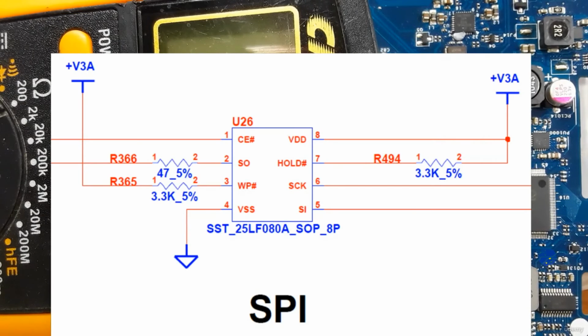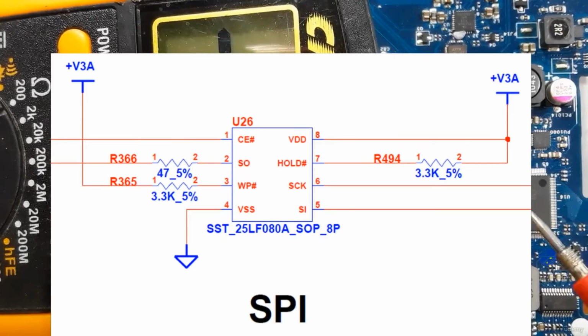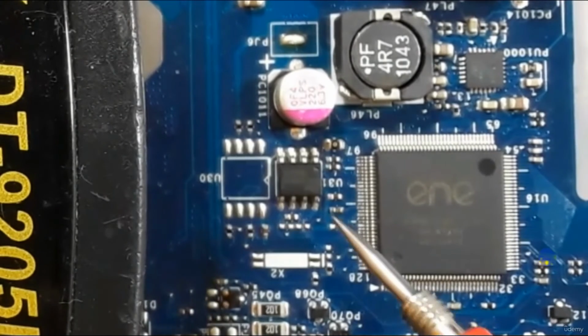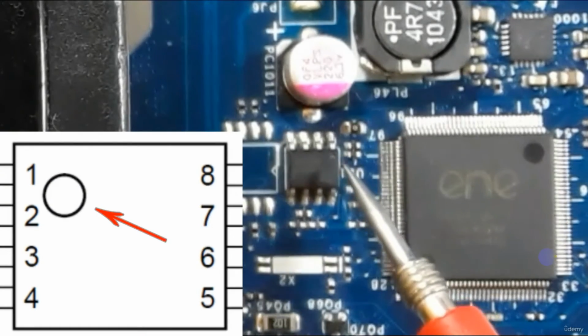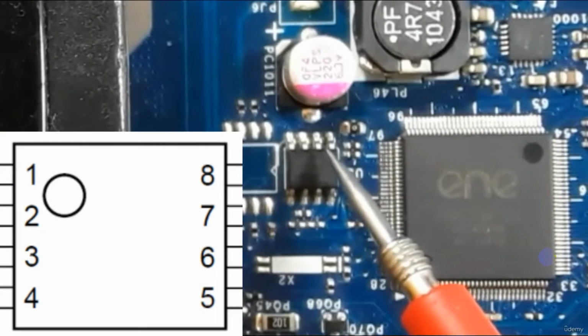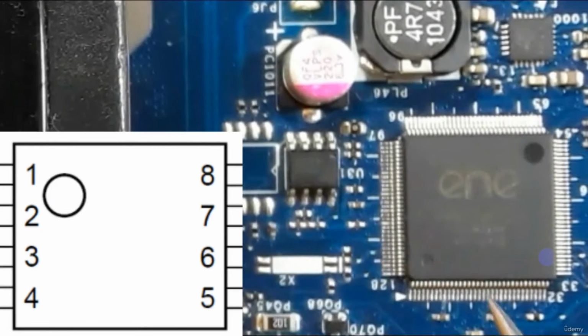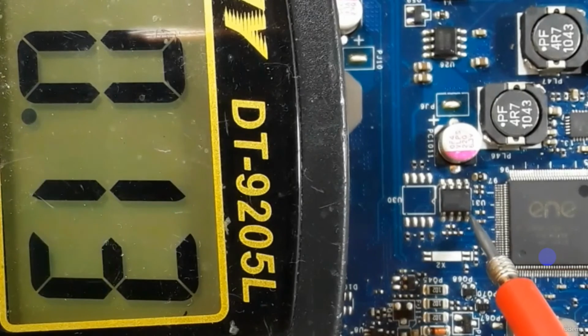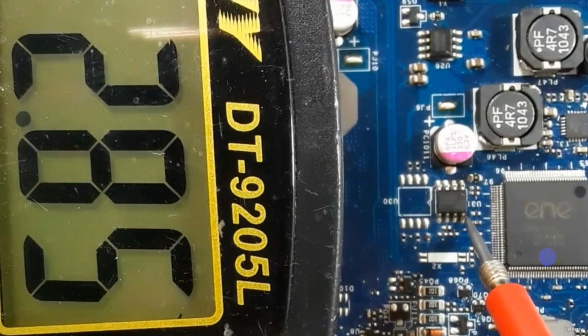As you see in the schematic, always you will find 3.3 volt in the pin number 8 of the BIOS without powering on the laptop. We have this dot here, means this is pin number 1, 2, 3, 4, 5, 6, 7 and 8. So let's check pin number 8. As you can see in the multimeter, we have 3.3 volt.